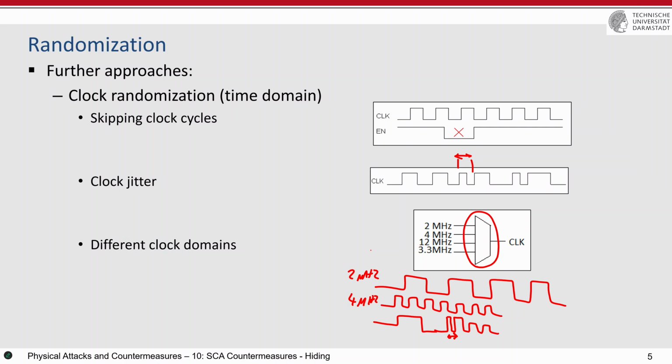Then this module is not a simple multiplexer. This should be dedicated to changing the clock, meaning that it should wait long enough to be sure that both clocks are exactly, for example, at the low level, or there is no clock glitch at all, and then at the safe time, it switches from one clock to another clock.